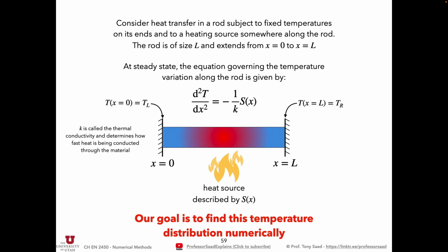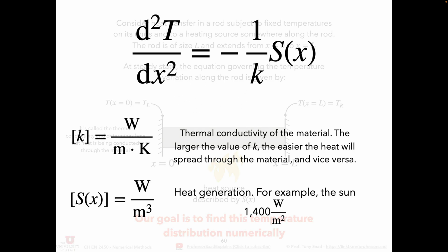That's why you put a gap or you put air in double glazed windows, right? Because air has a much lower heat transfer coefficient. So there's heat from the outside. The heat is trying to come into the house, but then it meets air, and the air is going to resist that heat transmission significantly. And then you have the second piece of glass on the other side, right? So that's what you learn from heat transfer. Very simple idea. So k describes that process.